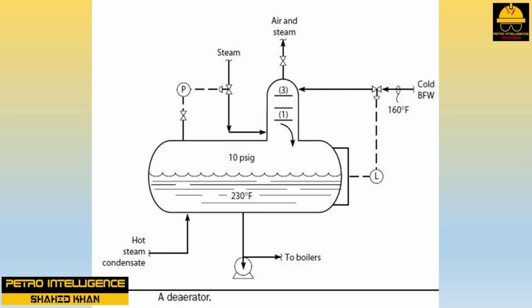Removal of the bulk of the calcium salts that would cause hardness deposits in the boilers is often accomplished by hot lime softening. If excess CO2 gas appears in downstream units consuming the steam, it is the fault of the lime softening, not the deaerator. This picture shows that the cold BFW has been heated to 160 degrees Fahrenheit, from the 90 degrees Fahrenheit lime softener effluent. This is an excellent way to save steam to the deaerator.